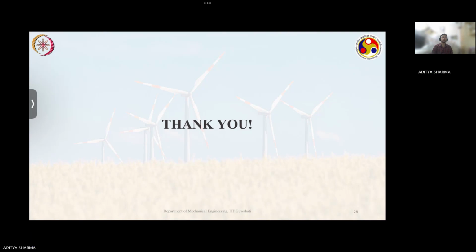Then after that, we moved on to wind energy, where we saw the potential the wind has, okay, in terms of kinetic energy, and how we can harness it using wind turbines, and what are the forces like axial force and torque that your wind turbine experiences, expressions for it, and the optimum exit velocity we saw for maximum power that can be generated from a turbine.